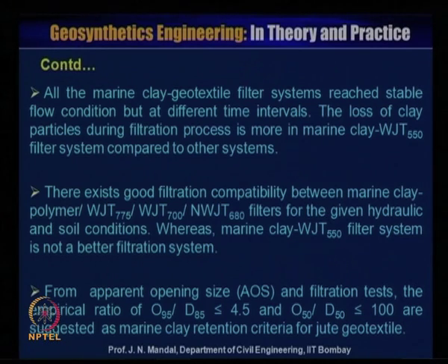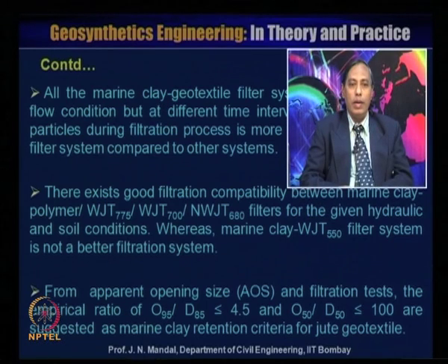There exists good filtration compatibility between the marine clay, polymer or natural woven jute geotextile 775, woven jute geotextile 700 and non-woven jute geotextile 680 filter for the given hydraulic and soil condition. Whereas the marine clay woven jute geotextile 550 filter system is not a better filtration system.